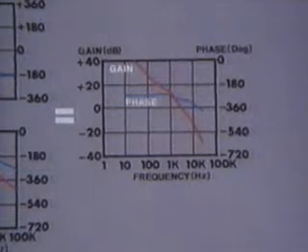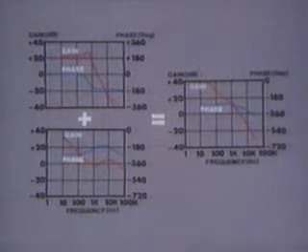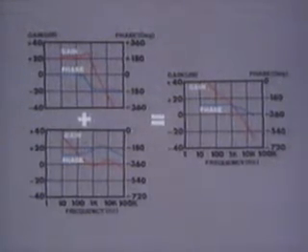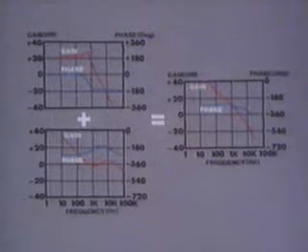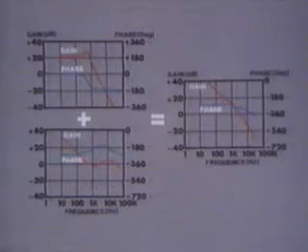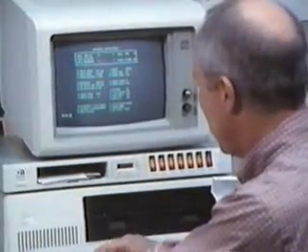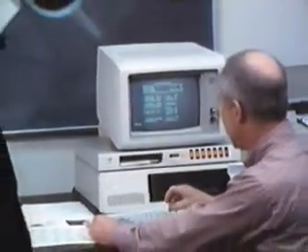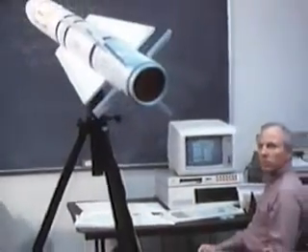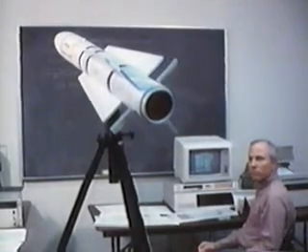For a feedback loop to be stable, the total phase shift must be less than 360 degrees when the gain is unity. The loop will also be stable if the total phase shift is 360 degrees and the gain is less than or greater than unity. When the gain is unity, the phase shift must be less than 360 degrees. The actual amount less than 360 degrees is the phase margin. But as we have discussed, just stabilizing a loop does not mean it has been optimized. The phase shift and gain identified on a Bode plot of a modulator can be utilized by the modern engineer to determine optimum crossover frequencies and phase margin for any feedback control system.